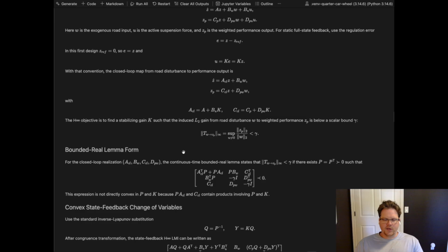There is one other little wrinkle, which is the linear fractional transform. On Wikipedia and other sources, you'll see a general P block, which is just the generalized state space that takes in an exogenous input and produces an output. Then you have the controller K on the outside, so you have a feedback loop with that K. The linear fractional transform takes that PK and packages it into minimizing that transfer function, and then you can break it out into that single line,